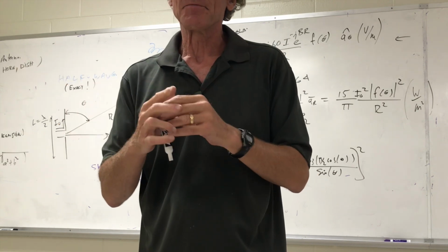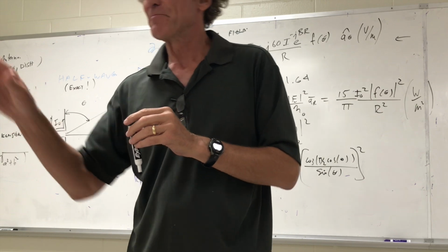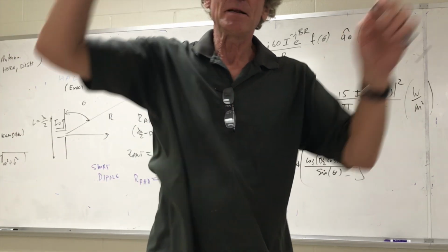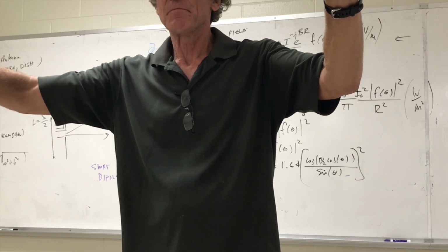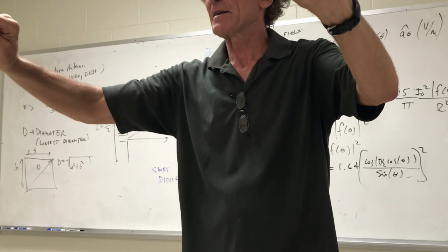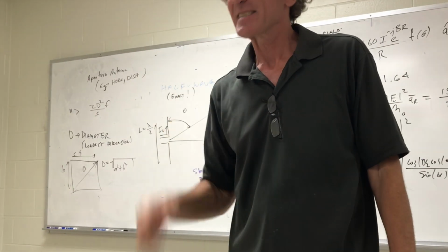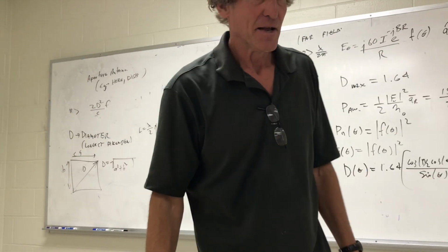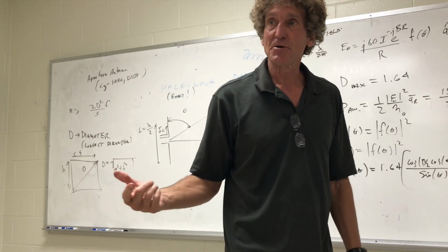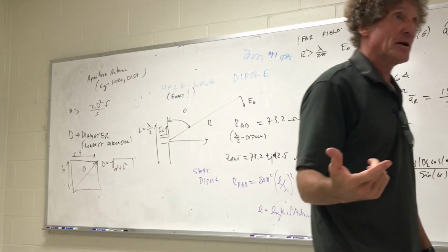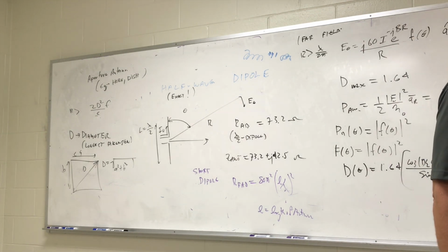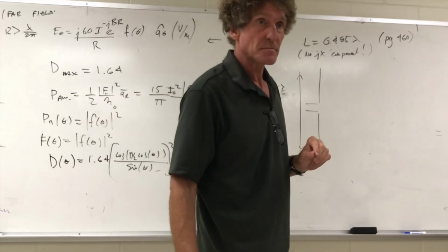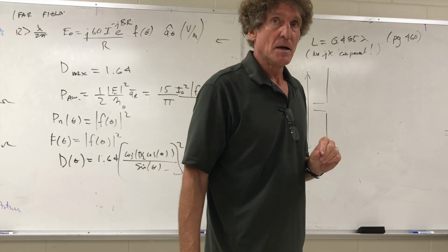And if you take some fingernail clippers, and I actually haven't done this, and you start snipping off a little bit of the ends of that wire, you have to tack it down, all of a sudden you see that reactive component go to 0 when it gets down to about 0.485 lambda. And that's one of the neat things you can actually do and see happening. And then you'd have no reactive components, so everything's radiated, or maybe some resistive losses, but that's it, there's no reaction.